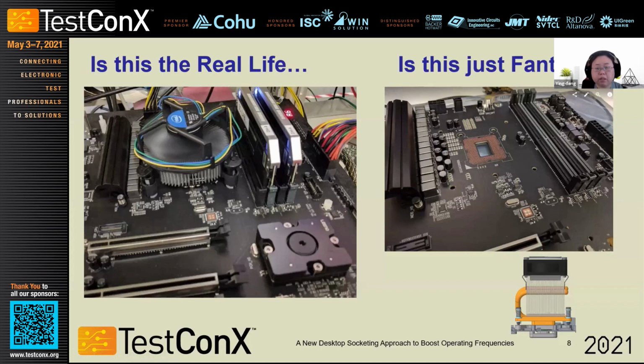Thank you, Emad. Will the heatsink differences, like the one that you were showing here, impact the performance results? Yes, this is a possibility. Actually, generally these validation heat sinks have better cooling capability. One thing that we did, we managed the RPM on the fan on this heat sink to the minimum possible, just to get performance to be hopefully on par with the original OEM heat sink.